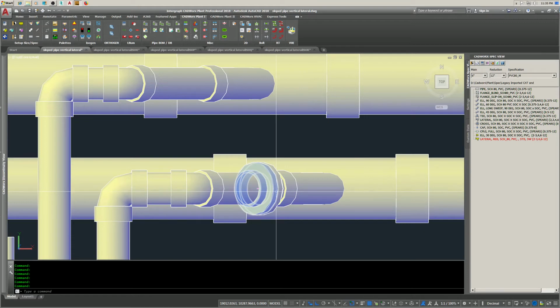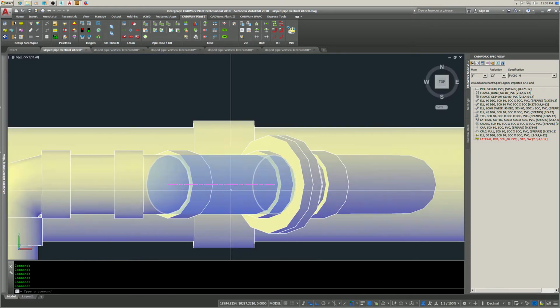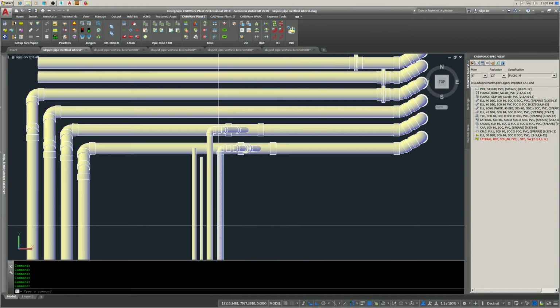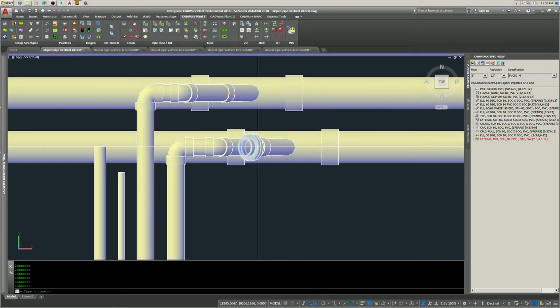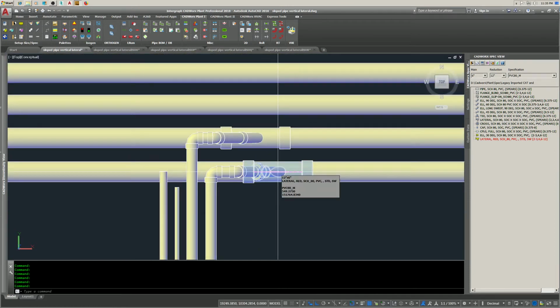And I put in a flange connection there. I didn't on this one, but this is, if this run is no longer needed, they can disconnect it, move the pipe instead of abandoning it in place, put a blind flange on that and cap it. You'd do the same if you were going to put in future connections with this fitting.